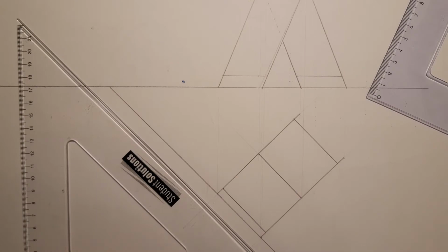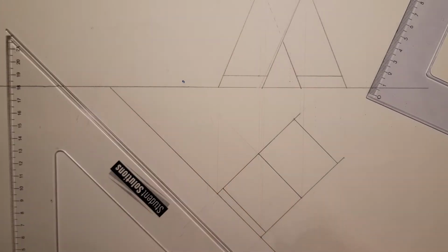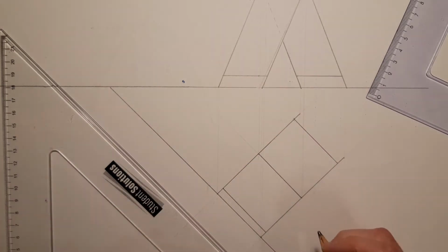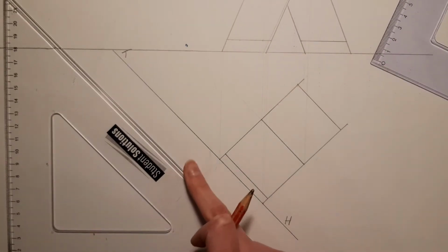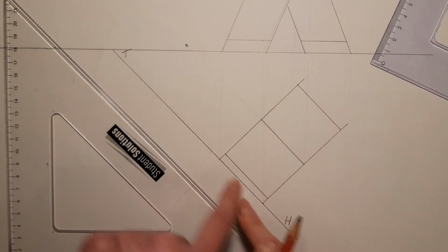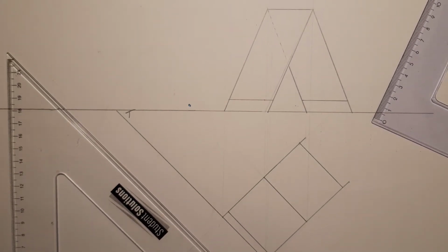I just noticed in some of the questions that you've been doing, you've been drawing them kind of light. The vertical and horizontal trace, it's a plane. So where it touches on the ground is going to create a line, and that is going to be heavy. So this is a HT, horizontal trace. And again, it's the 2 end points. These are on the ground. So there are 2 definite points on the horizontal trace, and you just continue it on. You have seen this time and time again.